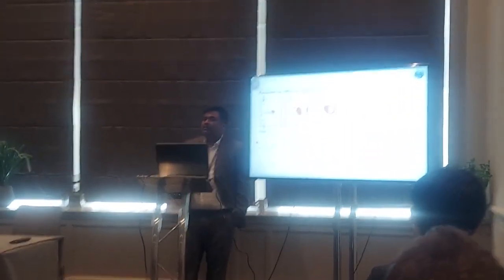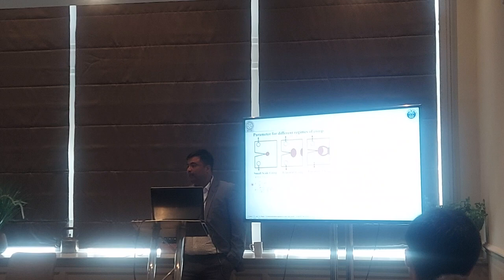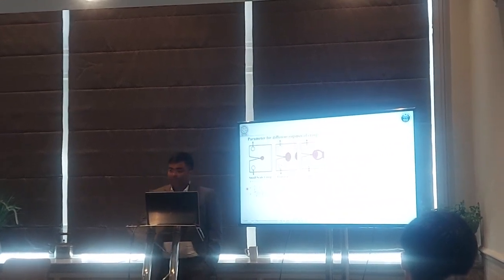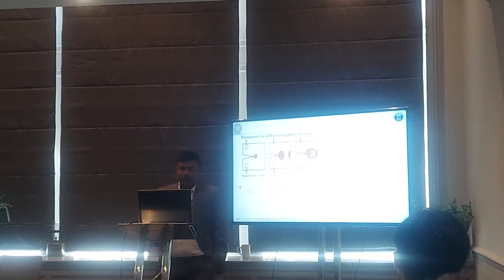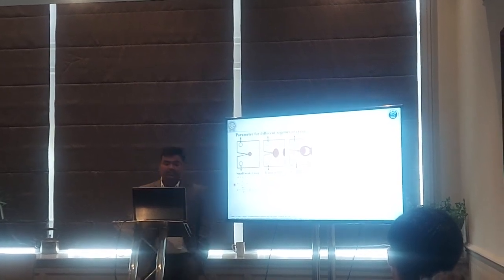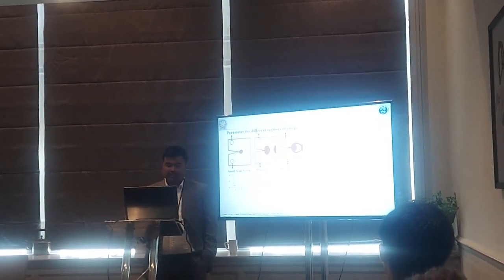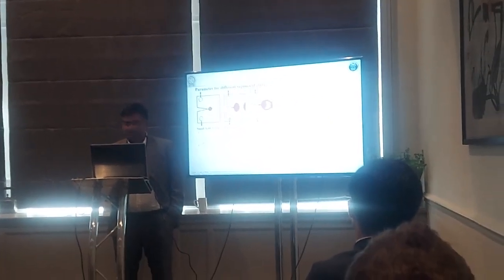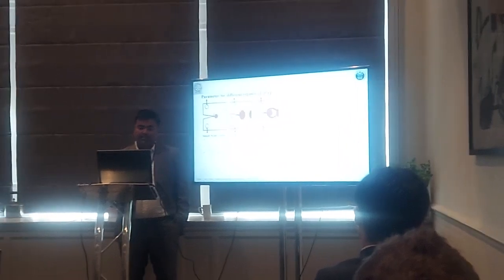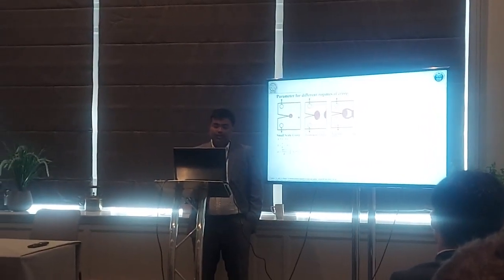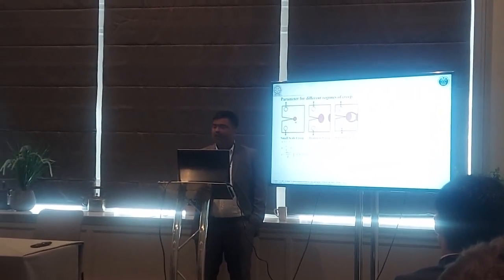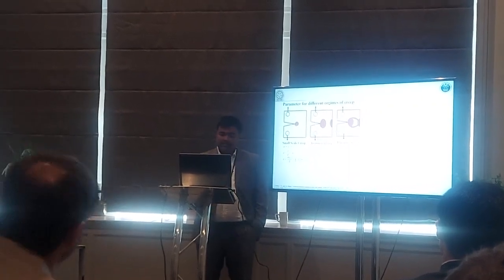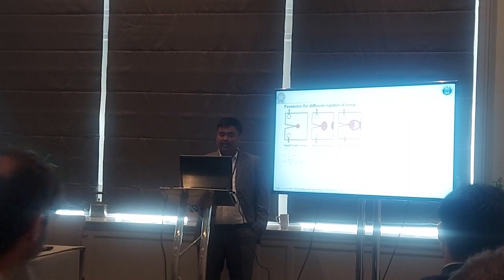So what are the different creep zones, and how do we apply the different parameters to characterize the crack in these conditions? We try to understand the different regimes of creep. Initially, when the material is loaded, very small creep zones form at the crack tip, and this size is very small compared to the ligament length.